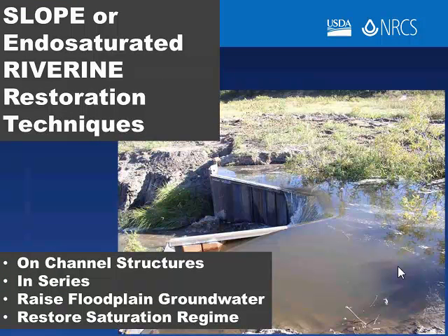This is an extreme case of a water surface profile modification practice in the Nebraska Sandhills, where a large deep channel has moved up through a wet meadow, and in this case, a sheet pile weir structure constructed in a cross vane orientation has raised the water surface about 3 feet and resulted in a pretty direct response of groundwater across a very large wet meadow.